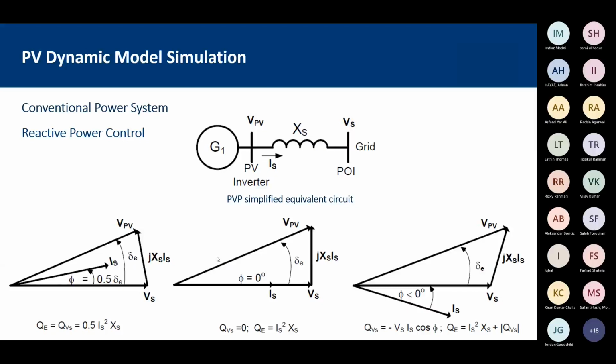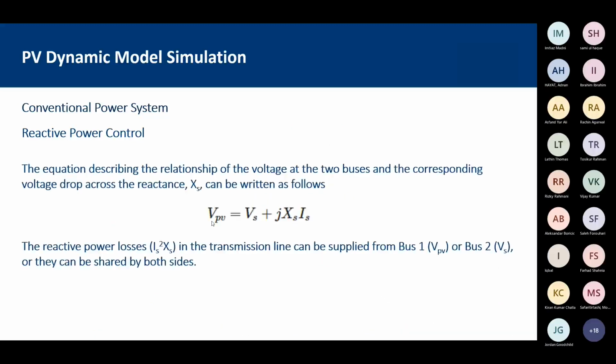The power angle of the output voltage mostly corresponds to the real current component, which is IP, and the output current will be IS, which is the voltage source current. Then we can control the angle by controlling the generator here. So that's a simplified two-bus system. Reactive power control is relatively simple.